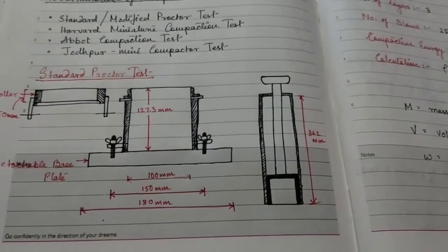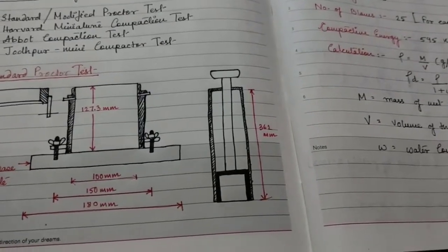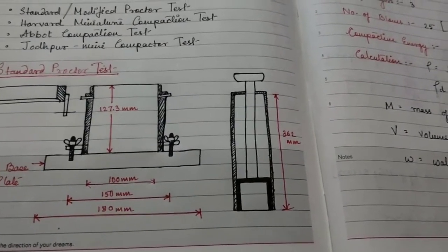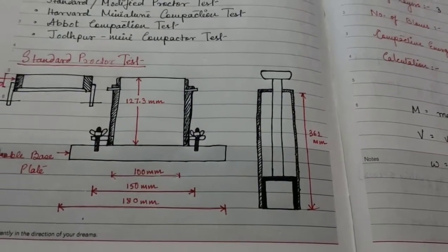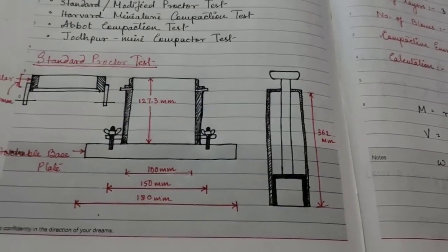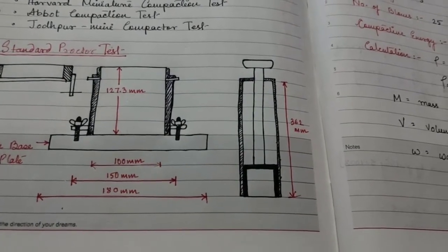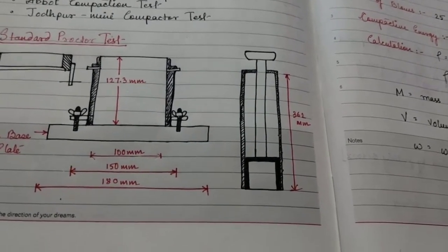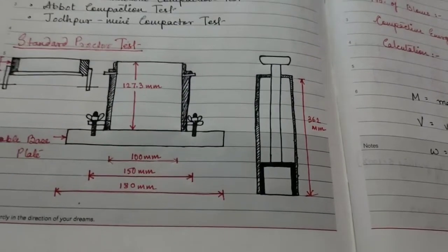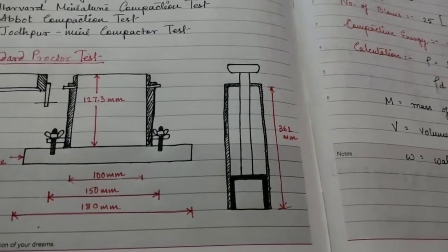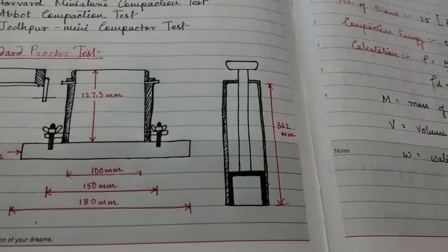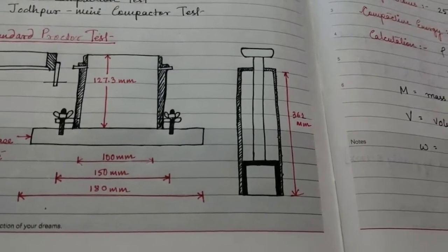This is different for different kinds of soils, and the maturing time is mainly permitted for proper water absorption. The initial water content that can be mixed with the soil may be taken as 4% for coarse grain soil and 10% for fine grain soil.